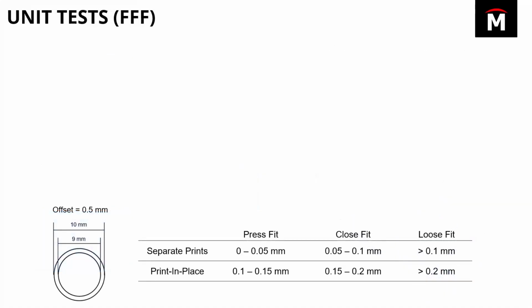Now people ask me, Joe, I don't know the tolerance of my printer. I don't know what tolerance I need to model into CAD. What should I do? And what I always recommend is to print a unit test. Now unit tests vary a little bit based on the printer technology. So with FFF printers, you've got two different types that you can use.